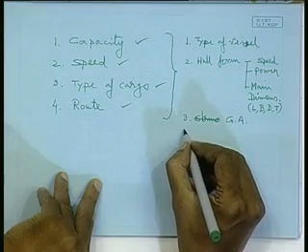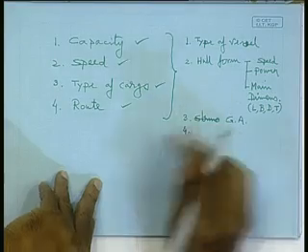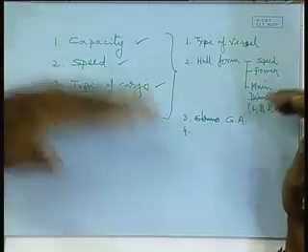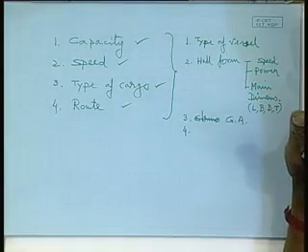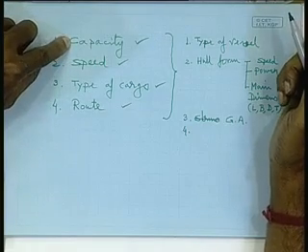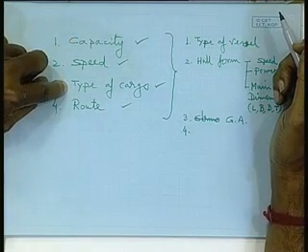So, once that is done, gradually it is coming to more and more detail, and through that you refine everything, your length, breadth, draft requirements. Because here you do the capacity calculation, and if you find that things are falling short, you will have to increase the length or the depth, so that your capacity condition is satisfied, cargo type condition is satisfied.